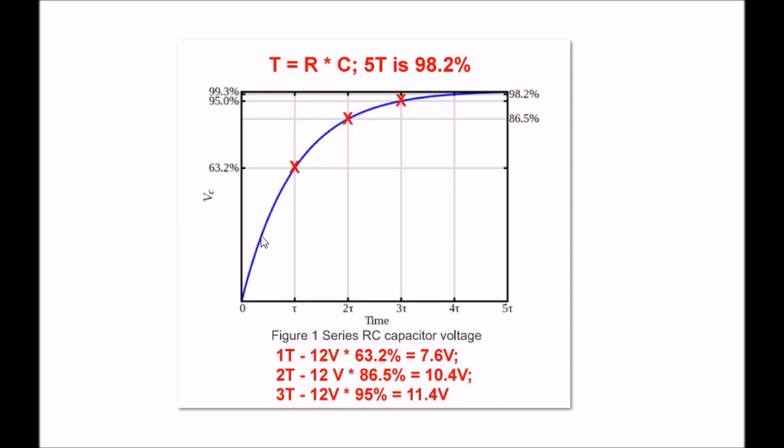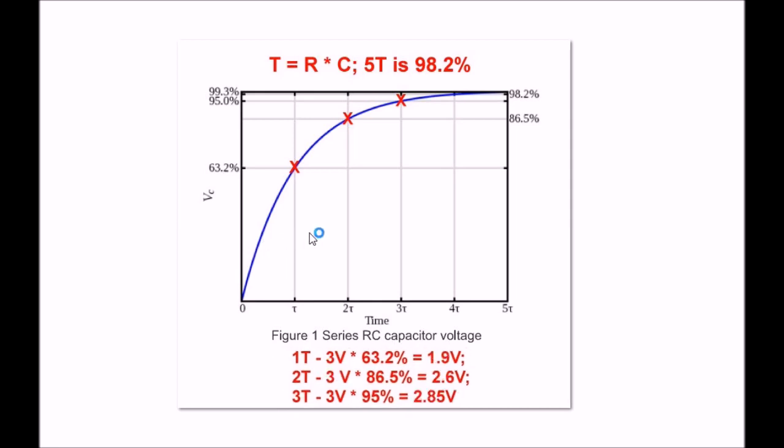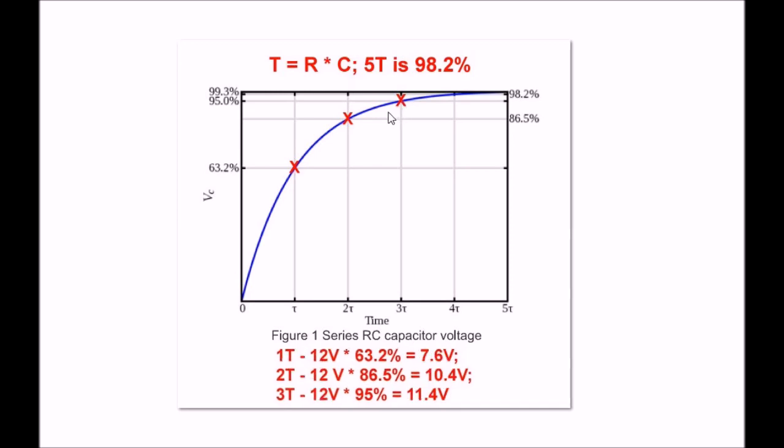Drive these things. Remember VGS. Do not exceed VGS. But with a higher voltage, you will switch on all of those MOSFETs very close together, and they'll be switched on fully and hard down in here at a fraction of T. Or you can sit here at 3 volts and take up to 3T, 3 time periods, to try to switch it on. It's up to you on that.